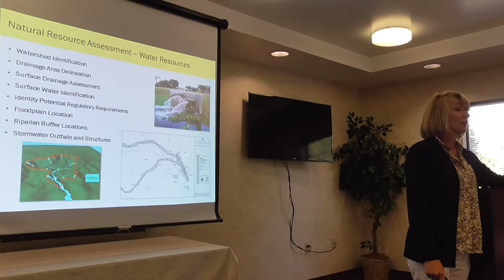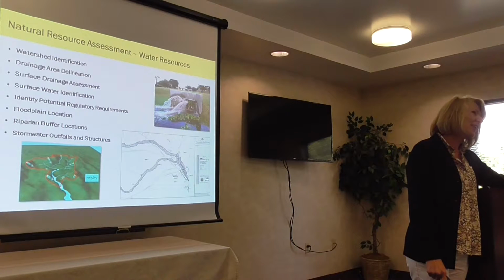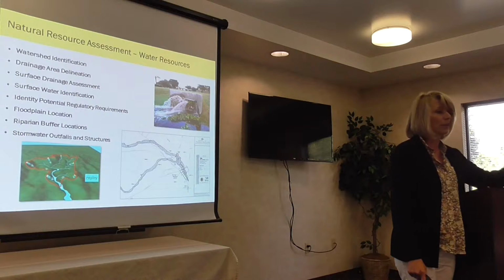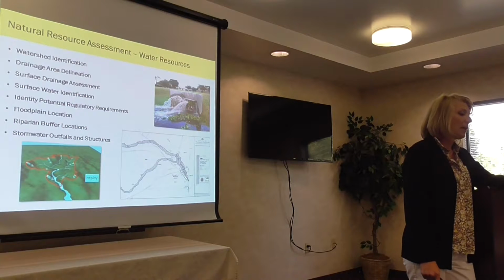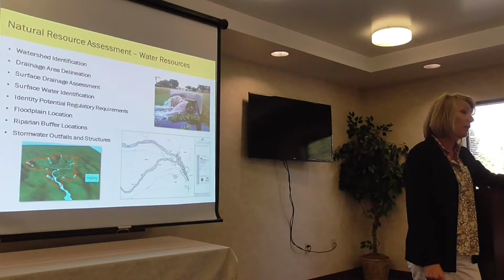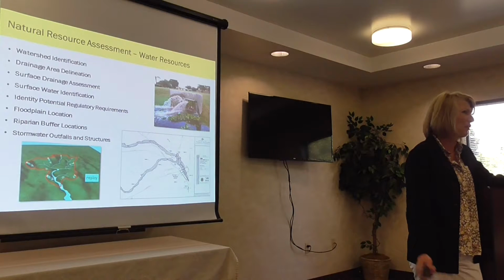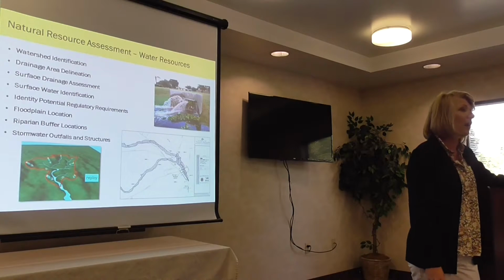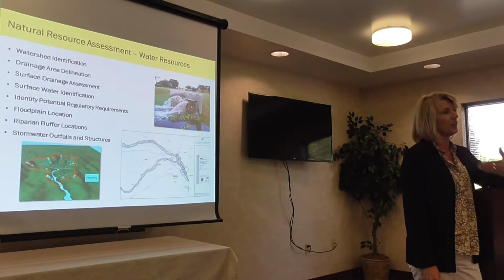To a degree, you can rely on One Call. We have not had a lot of success with One Call, and we've gotten to the point where we don't rely on it completely. It's necessary, PA One Call, from a design standpoint to get an idea as to where utilities are. But typically, we've started to use an actual private company that does utility locating. Does anybody use any of these groups? We've been using Master Locators. I think there are some other private groups out there, and they go in and identify all the utilities on a site.